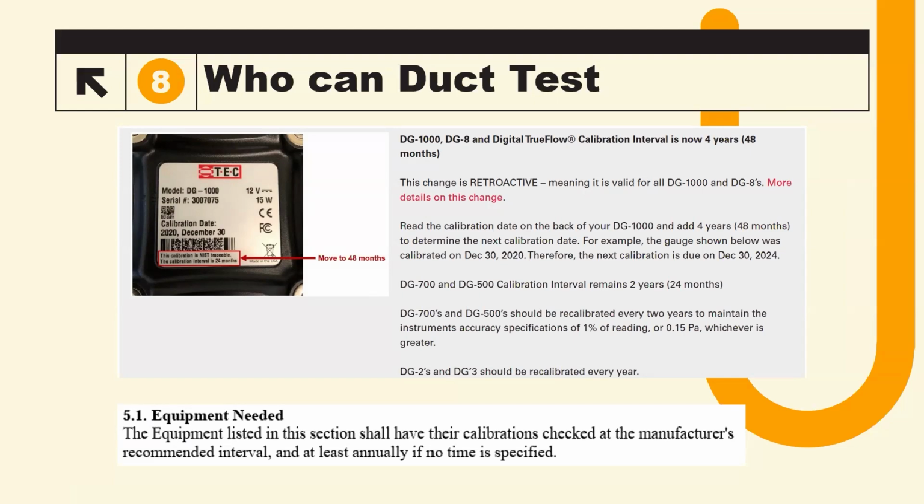The manometers used for these tests are pricey. The newer ones are fully digital. They're subject to fewer calibration issues, but the older styles have internal components that just one drop on a hard surface like concrete can damage, requiring recalibration or repairs, or at the very least, it becomes wildly inaccurate. And you may not know it by just dropping it. There's no way to tell if that is accurately being done.